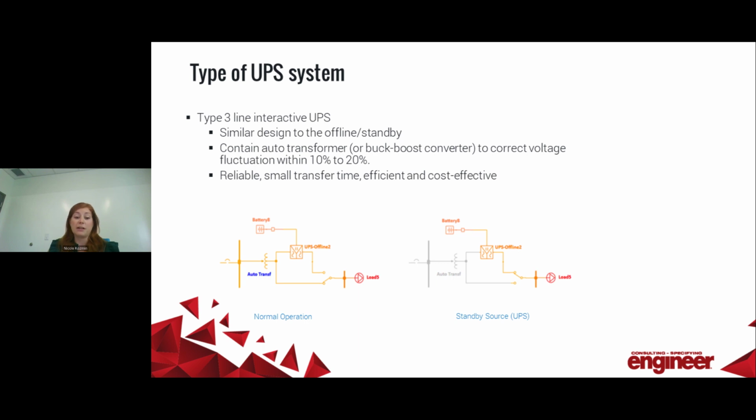It does have a small transfer time. It's really suitable for smaller, less critical applications such as PCs, telephone systems, non-critical networking equipment, and small motor loads. So it will not protect you against those harmonics and frequency variations, but you still will be protected against sags, burnouts, surges, spikes, transients, electrical noise, and main power failure.